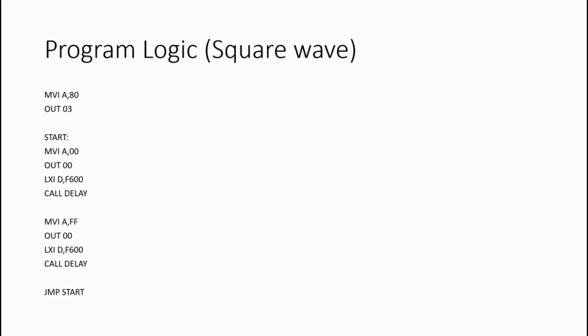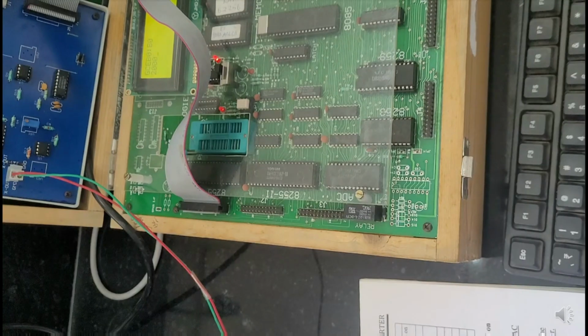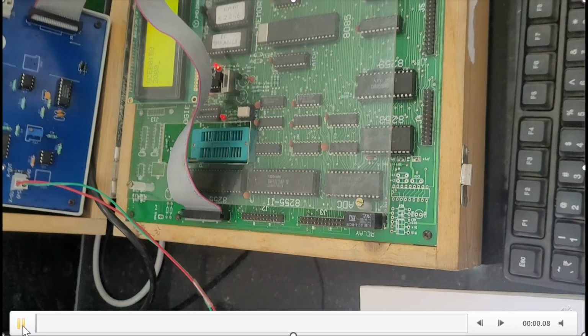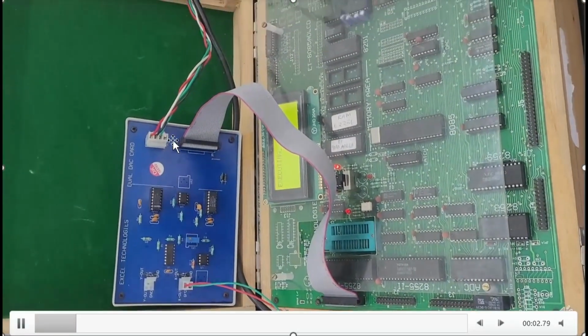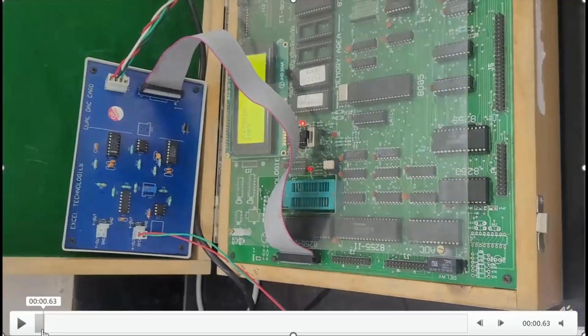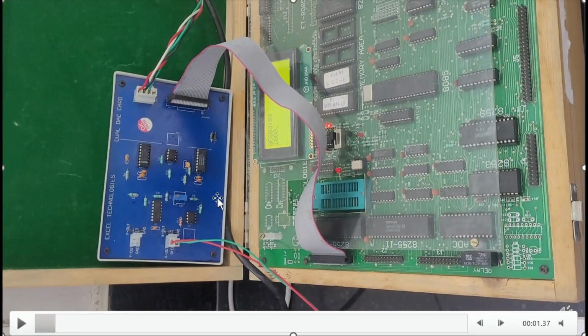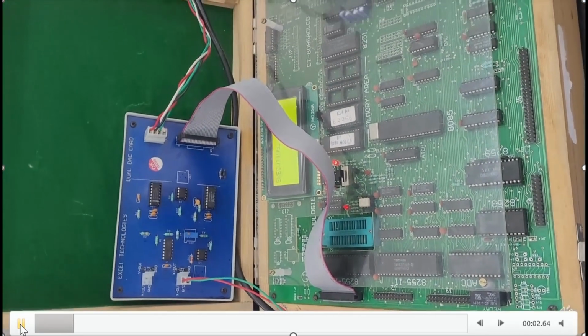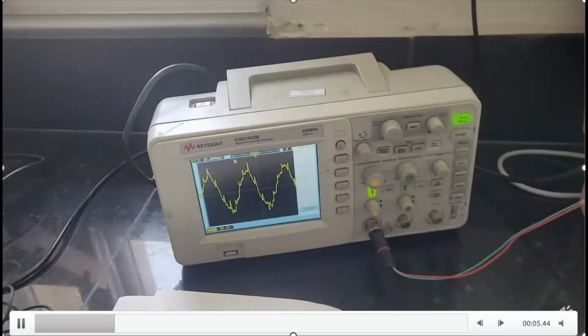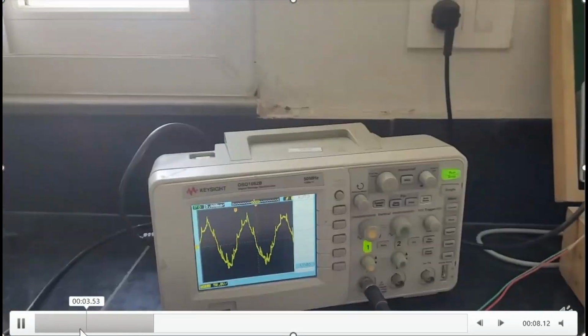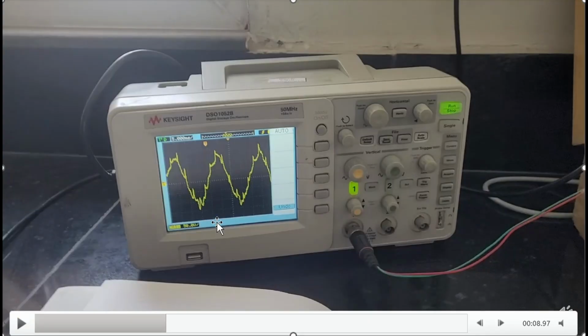Now let's look at the waveforms and the videos which were recorded in the lab. As you can see, this is the video. Now let's play it. This is the fuzzy cable. I just entered G2000 here, and then I pressed Shift and 4, which caused the program to execute. You can see a sine wave here, which doesn't actually look much like a sine wave because of some fluctuations. I entered the lookup table of the sine wave, and this is the output that I actually received at that time. There could be many reasons behind this.